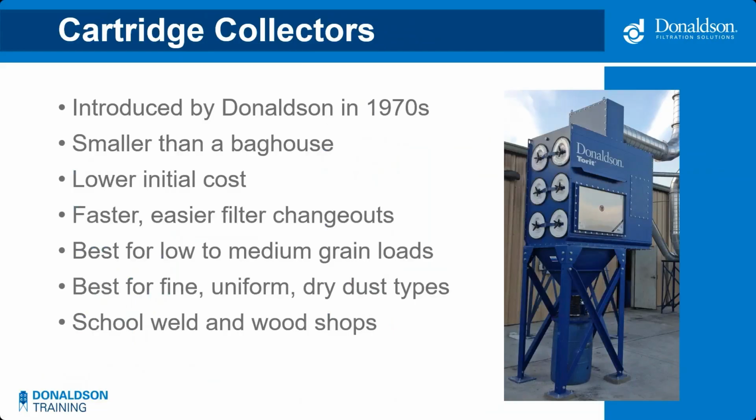A high percentage of collectors sold in the marketplace today are cartridge collectors due to their small size and lower initial cost. And compared to a traditional bag house, the filters are much faster and easier to change out. They are best for low to medium grain loading, as well as fine, uniform, dry dust types, like what is generated during welding applications.